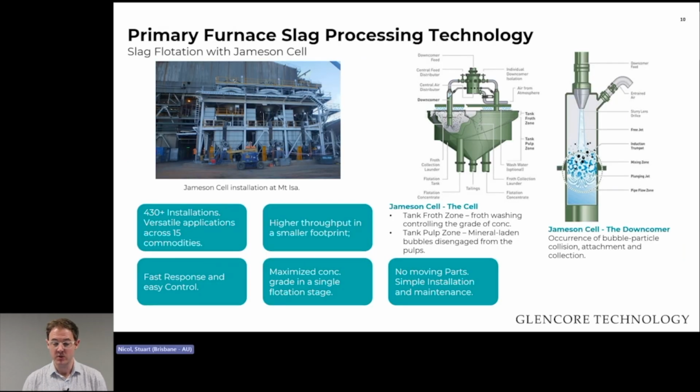If we look at the Jameson concentrator for slag flotation, this is one of our other technologies we have within Glencore Technology. What this does is flotation of your materials. Within the slow-cooled slag, you have droplets of entrained material, and also you form some on cooling. The majority of the copper losses to the tailings in conventional tank cell flotation has to do with ultrafine particles, which is a sub 20 micron fraction.